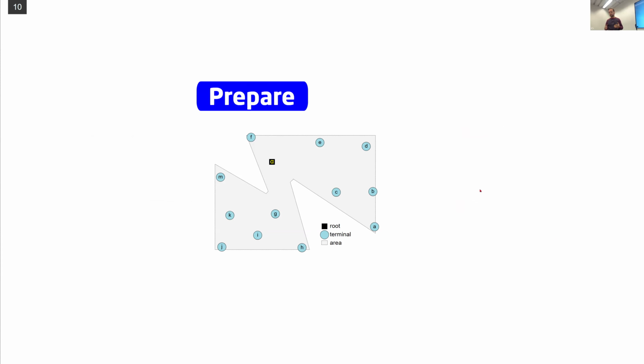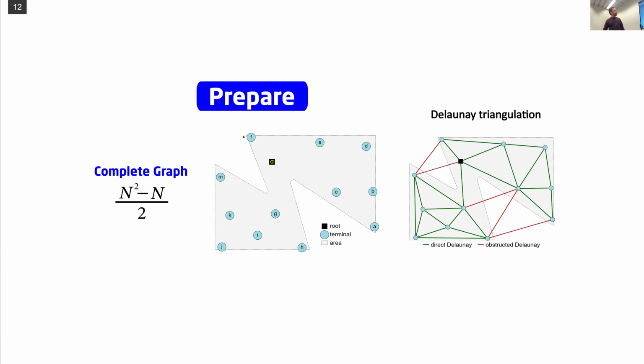So that's what you get in a given loop iteration, a set of positions. And this site has this additional constraint of not allowing cables in that area here. If you were going to look at all connections between nodes, you'd have something that goes with n squared. But then we are going to reduce that and use the Delaunay triangulation as a starting point for reducing the edges. And now here we already identify the direct connections that would not be possible because of obstacles in the way.